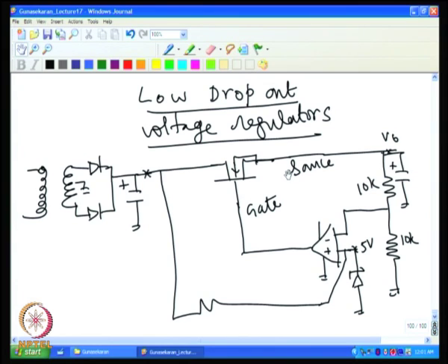This is one of the drawbacks of the MOSFET, because with a transistor, one can switch on and off with 0.6 volt, whereas the MOSFET needs extra gate and source voltage, which may not be available in low voltage instruments. That is why the MOSFET is not extensively used in low voltage power supplies. Now, in this case all that is required is that I give a supply voltage here much higher than the 10 volt, at least 20 volt power supply required.